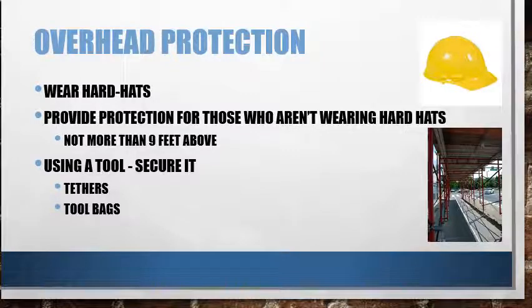Let's talk about overhead protection. Always wear your hard hats whenever there is height-involved work that something could fall off of and strike you. Provide overhead protection for those who would not be wearing hard hats, who might wander into the work site. When you can't create a controlled access zone, set up protection for those who aren't wearing hard hats.